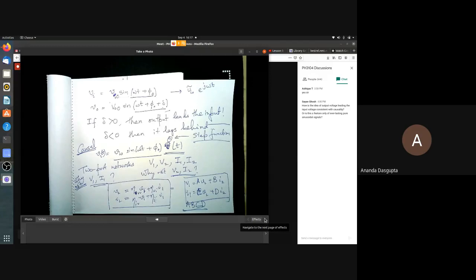The trouble is, for transmission lines, for example, things which stretch from the power station to your home, a description where you have access to both the input and the output and you can control both of them together is really not a convenient one. It's much more convenient to try to describe it by doing experiments, say, only at the output end or only at the input end. Which is why transmission lines typically use this kind of parameterization where V1, I1 or V2, I2 are taken to be independent.